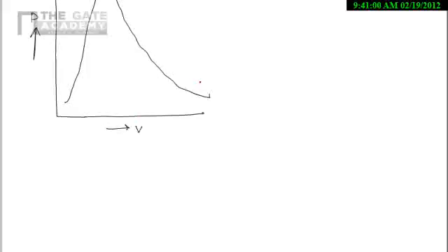If you see in the compressor, that is isentropic compression from 1 to 2. So I am representing the isentropic compression here from 1 to 2. Here the entropy is constant. From 2 to 3 it's a constant pressure heat rejection, and 3 is a saturated liquid state.